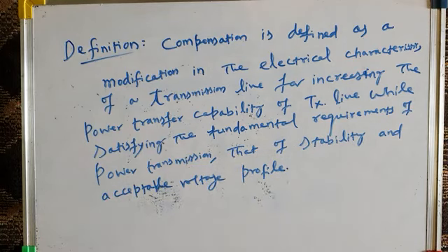I have a transmission network. I want to improve its power transfer capability, so I am using compensators. So what these compensators actually do, they modify the electrical characteristics of the existing transmission network so that the same transmission network transfers more active power. Its power transfer capability increases.